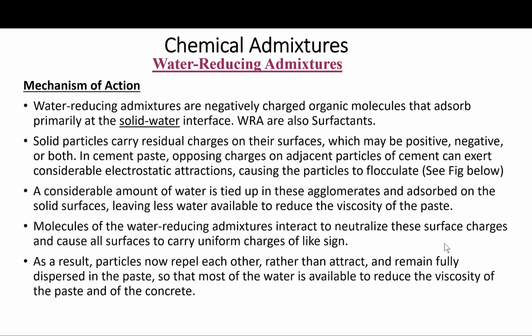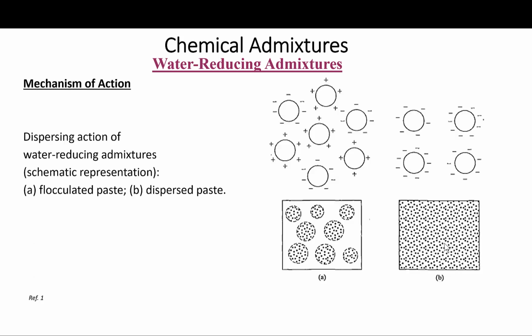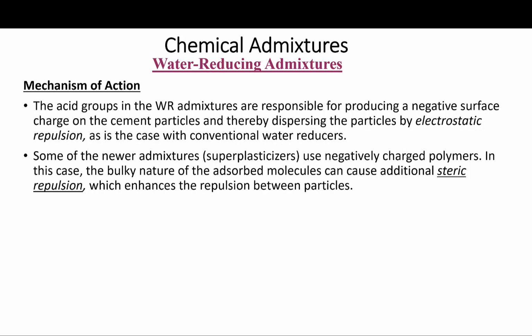The solid particles basically carry residual charges on their surfaces, which may be positive, negative, or both. And in the cement paste, opposing charges on adjacent particles of the cement can exert considerable electrostatic attraction, causing the particles to flocculate, as you can see in this figure. I'll come to it in a minute.